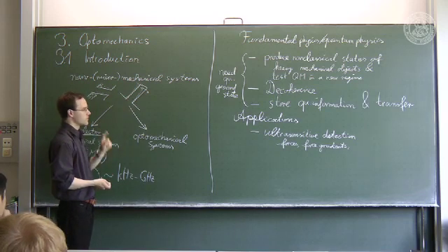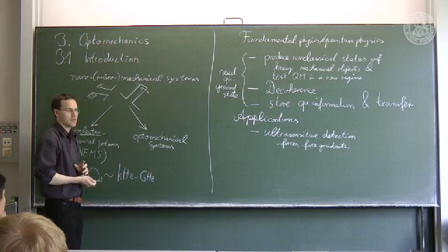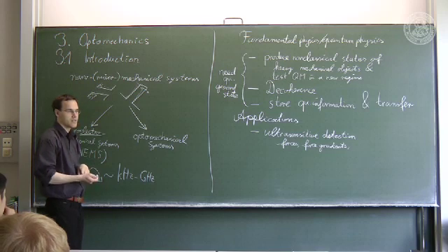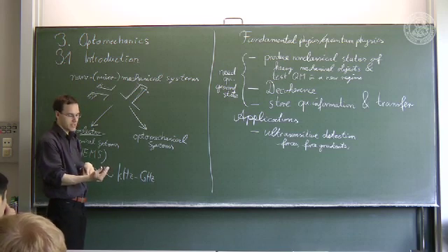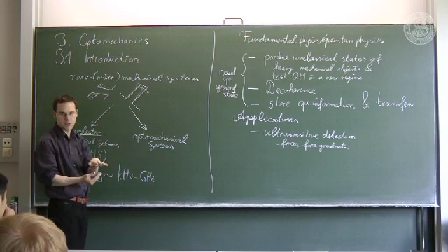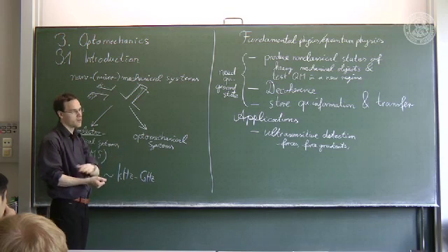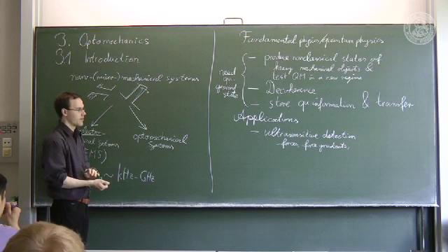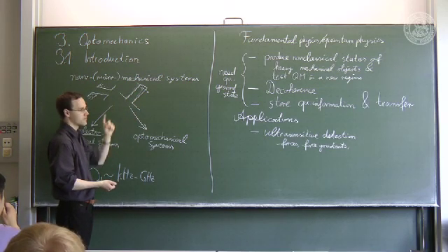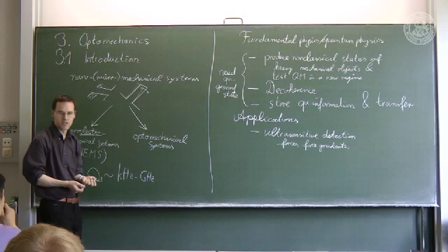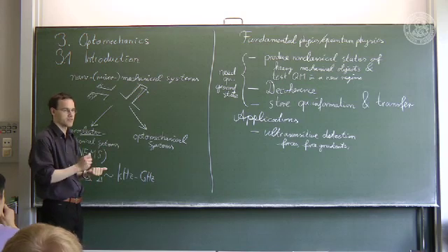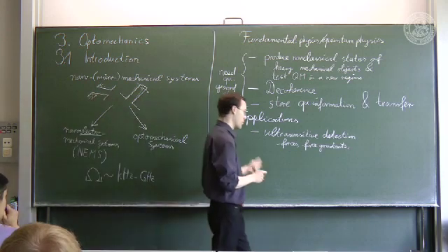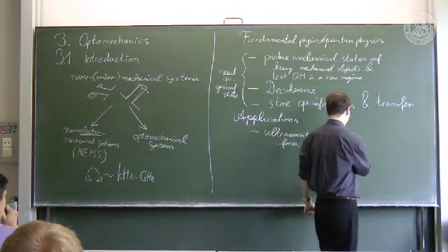And that is really useful, for example, in chemical diagnostics, because you can place some molecules on the surface of the cantilever such that they only bind with other very specific molecules. So if you have a gas of molecules coming nearby, only a particular species of the molecules will bind to the surface of the cantilever and thereby change its mass. So you can use this really to detect different chemical species. And that is being done. That is one of the big applications of these cantilevers.